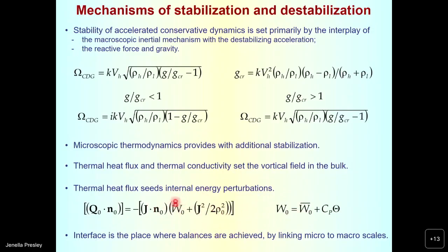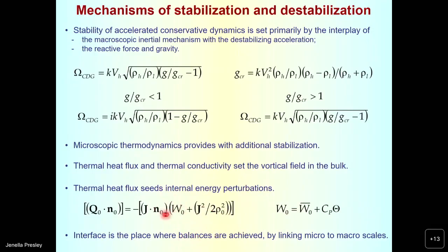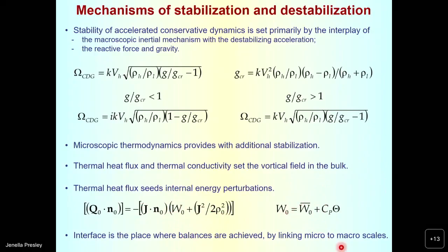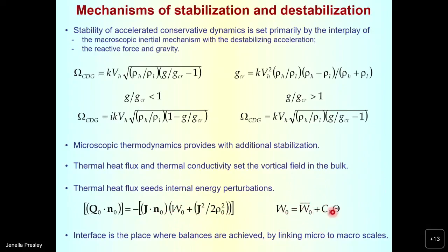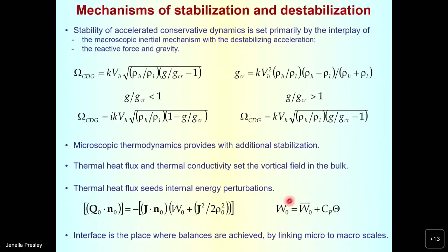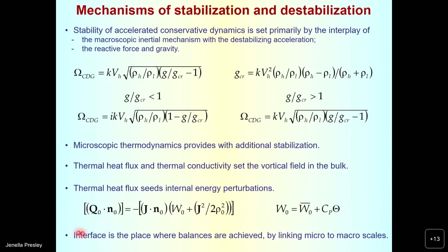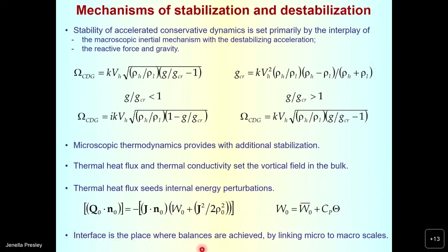Traditionally, we may think of that as an enthalpy of formation, which in my case is defined as W naught with a bar. But it's a more delicate creature. Essentially, we need to take our entire energy, deduct from it the enthalpy of formation, deduct from it Cp times temperature, deduct from it our kinetic energy as a whole, and only then evaluate the characteristic energy perturbations.